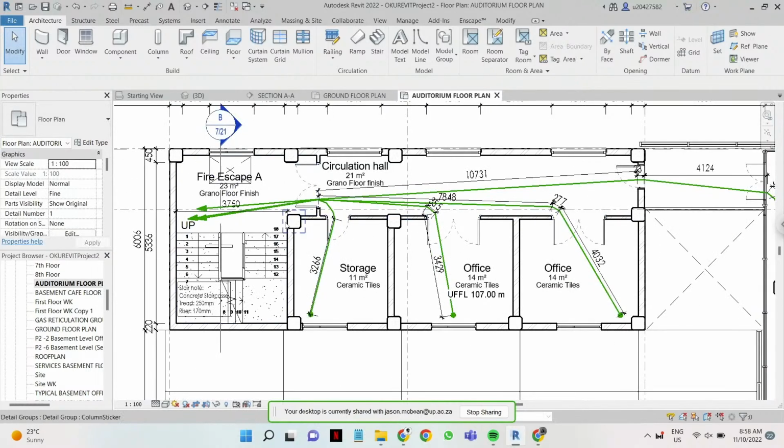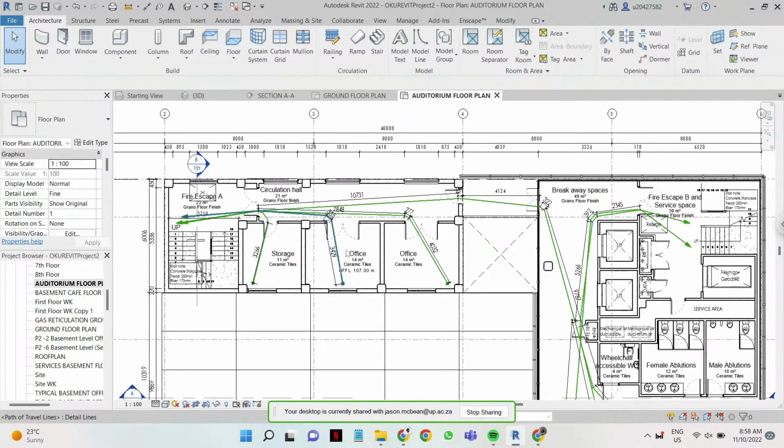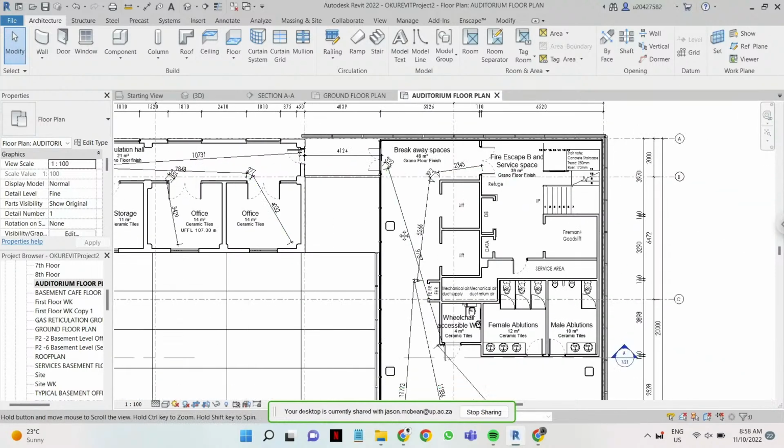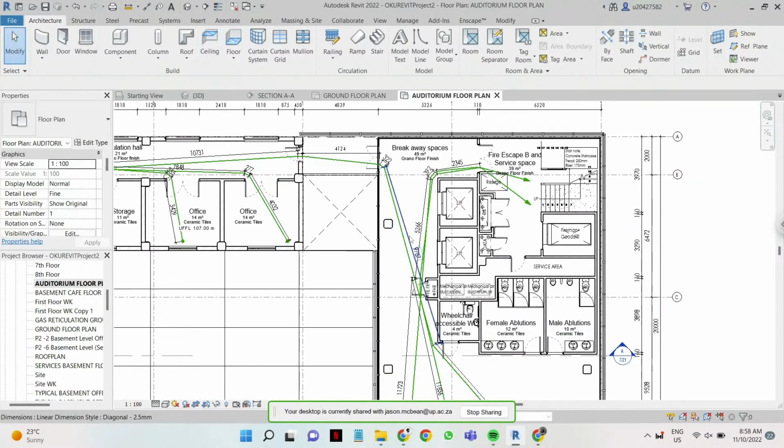And if you have a step between a passage, you draw a line at the step, and then you show the 2 levels right next to each other. So the contractor knows there is a step here in between. We don't show it everywhere, just where there's level changes, and we just show them from time to time so the contractor knows. You'll draw his attention.